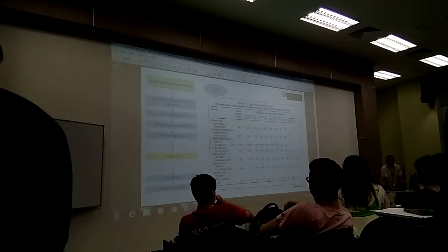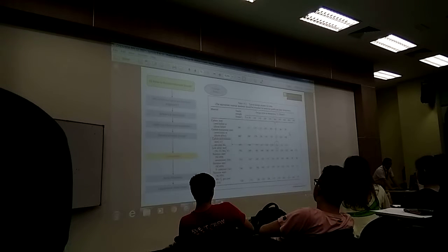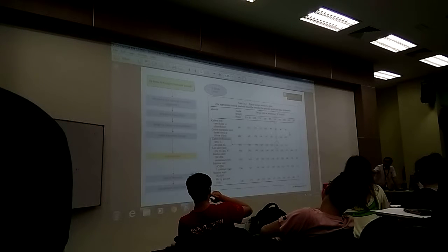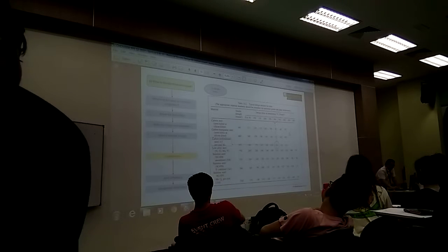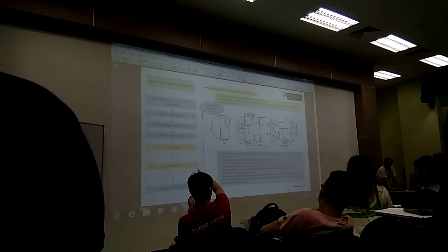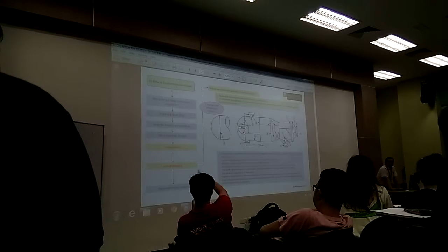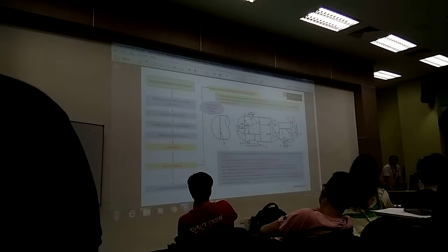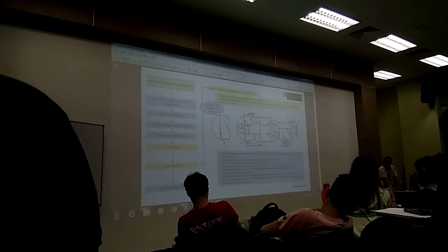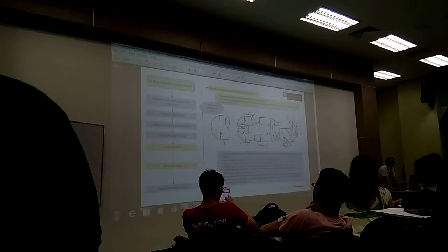And then design stress, how to get the design stress, this is very easy. It depends on your material of construction and also your temperature. Okay, and then classifications of different welding joints. We have 4 types: category A, category B, category C, and category D. Who knows, maybe this will come out in the test. We need to categorize the welding joint.